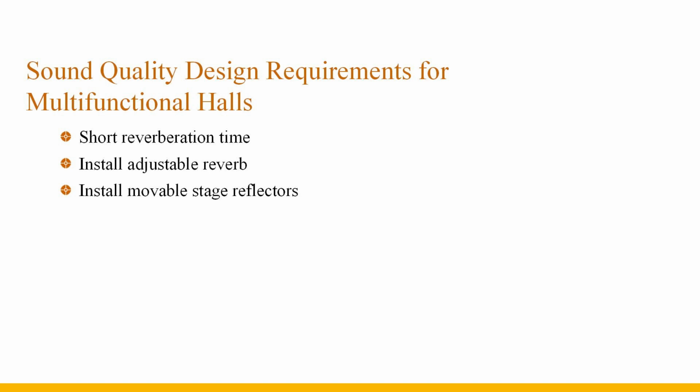The method of changing the reverberation time of the building is to make part of the ceiling or wall in the hall into a movable structure that reflects sound on one side and absorbs sound on the other side, and expose the reflecting surface or the sound-absorbing surface as needed. Specific forms include rotating, opening and closing, suspension, curtain, lowering, and so on.